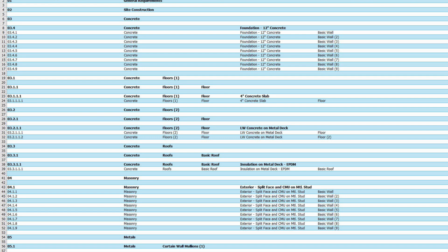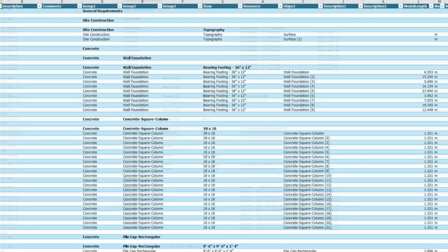Navisworks Managed 2024 was used to perform the quantity takeoff. CSI 16 was the catalogue used to organise the quantity takeoff. For the structural model, sets were made for items constructed of the same material. This allowed the cost estimator to estimate the cost of groups of items by using material cost. For example, the steel columns were grouped together with the steel bracing for the roof and floor.